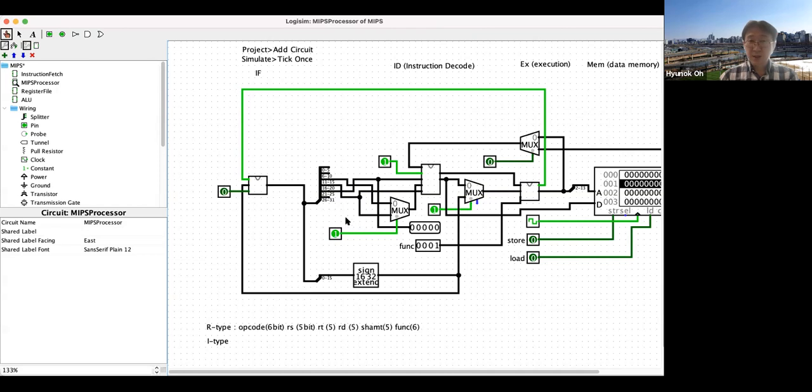And if you are looking at this, I think this is the source register. First one, this is source register. Source register value is 0. Okay, so 0 is coming out, and destination should be 1, right? So the $1 register should be updated. So this should be 1. If this is 0, then an incorrect value is coming out.